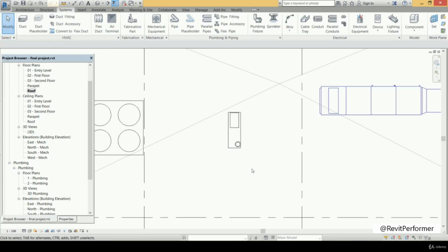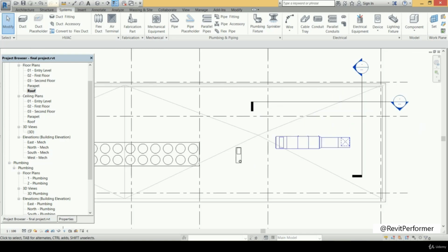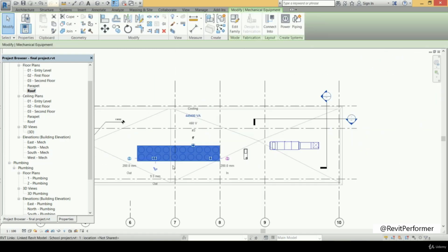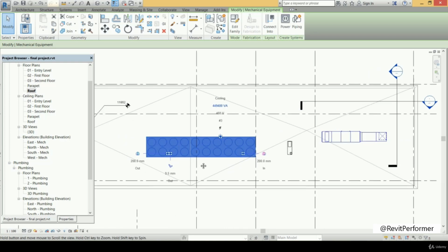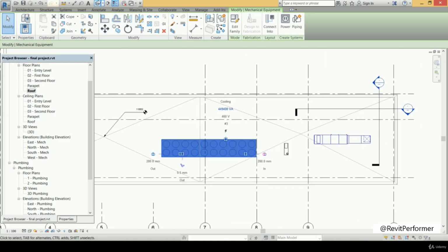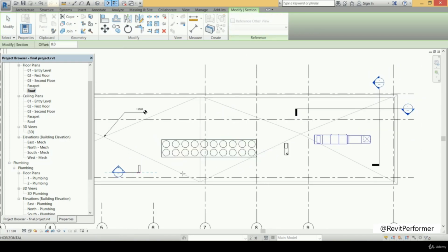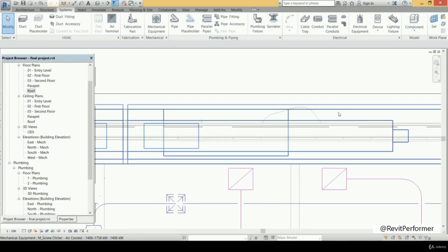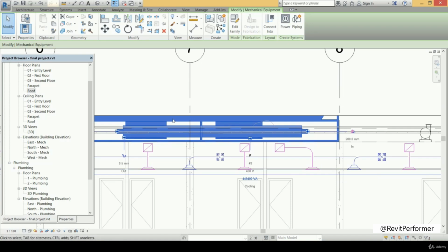And the output pipe of the pump itself is connected to the input pipe of the air handling unit. And for that, we need to make that required routing operation. And for that, we will access the chiller that we have, and we will access its output pipe. But for that, we need to make another section. So we go to the section tab, and we start from that point to that point. And then we access that section, and let's zoom in. Now we access the chiller, and then we access its output pipe.